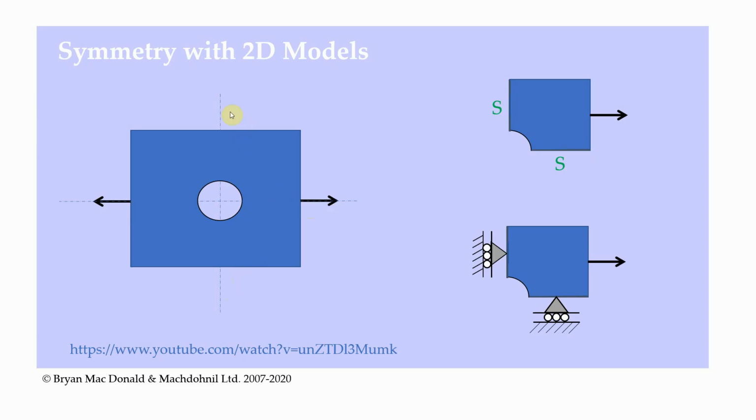So we have our geometry that's symmetric and also our loading that's symmetric. Again, if we were just to take this cutting plane first of all and just take this half of the plate and load, it would be symmetric across this way. But we can also take this cutting plane as well and then divide our load in half, because it's applied over just half of the line on the edge here. So we can model 1/4 of the plate, scale our load by half, and that's essentially the same as modeling the full plate with the full load on either side.